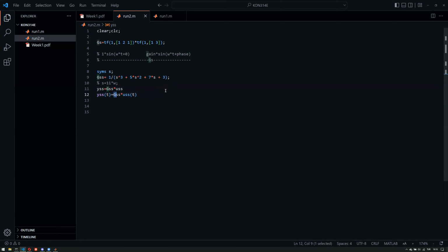So yeah, and the inverse Laplace of this is obviously going to be something else. But what I really mean by this is that we have the Laplace transform of the output in terms of input times the transfer function. And if we plug in s equals j omega, the integral that we use for Laplace transform and inverse Laplace transform will become Fourier transform and inverse Fourier transform. So this is quite important and amazing, if you ask me, because we can transition into the Fourier domain somehow.